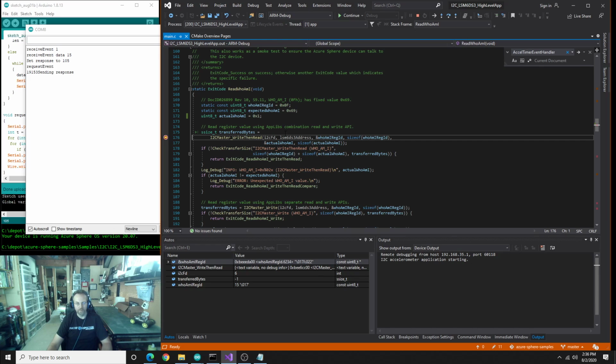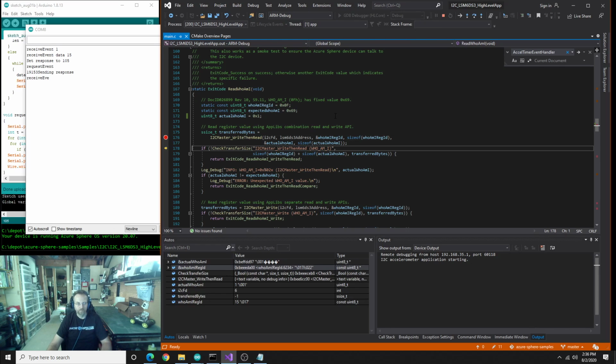Okay, so we're here. Our current actual is set to a 1. So F10. Our transfer bytes is -1. So we got that it timed out. So it says nothing got transferred. We saw it actually did transfer 1 byte, which was the 0x0f, that 15.